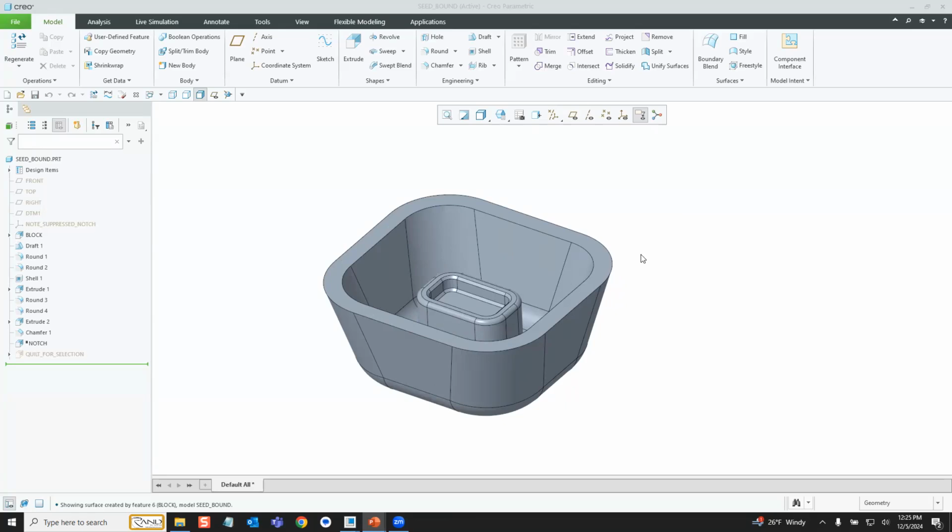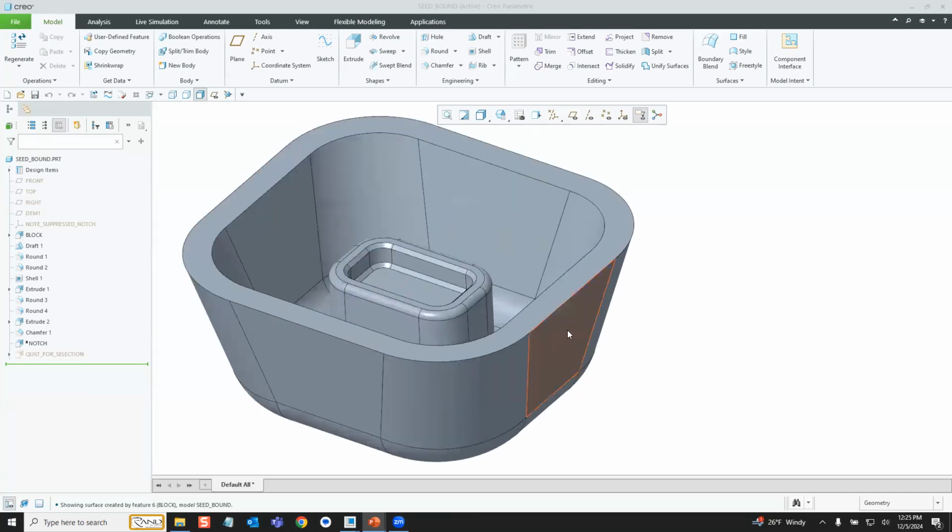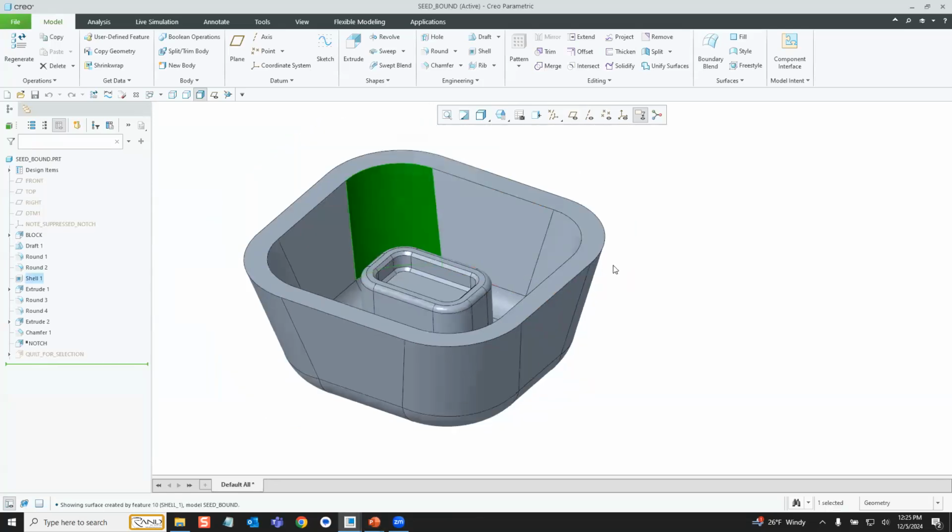Here, I'd like to pick all the inside surfaces of this container. So pick any one of them. It doesn't really matter which one you pick here. And I'm going to start with that surface. Then to have Creo pick every surface that touches that one as well, every surface that touches that bigger set, up to but not including the boundary, I need to hold the shift key now and pick my boundaries.